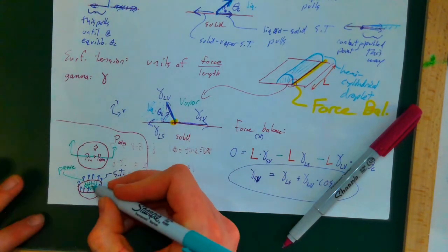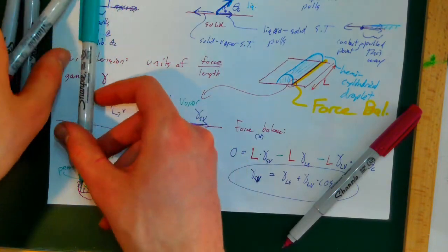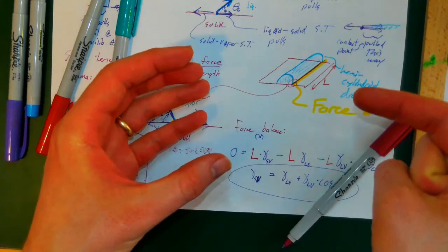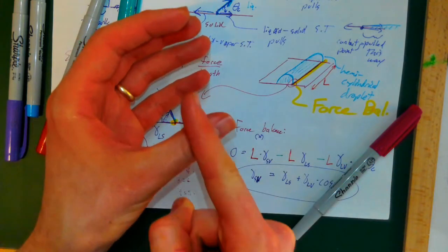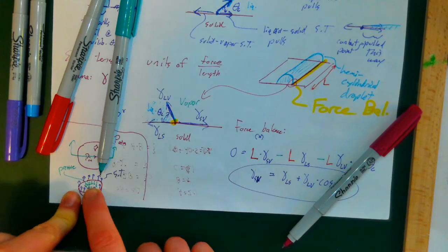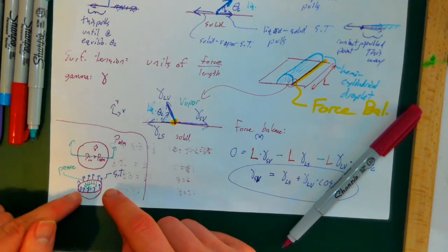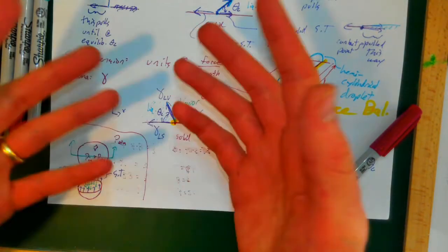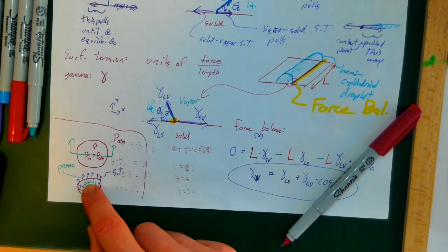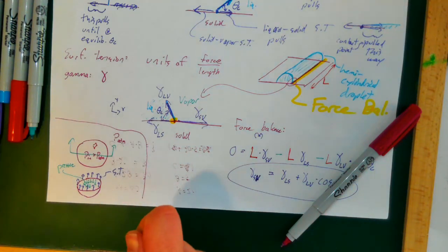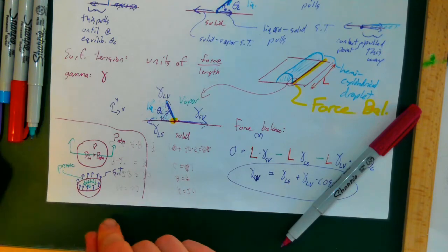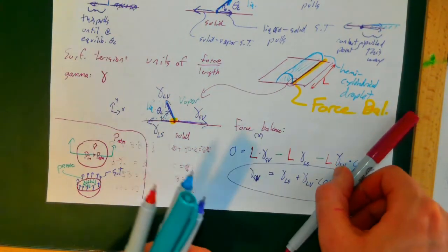So basically, pressure is pushing on the inside, and this happens both with bubbles, that's a thin liquid film with gas inside and gas on the outside. This is why when you pop a bubble, the bubble actually pops outwards. It's because it's pressurized inside. And this also happens with liquid droplets too. So if you're trying to create emulsions or things like that, it's actually higher pressure inside of a droplet compared to outside. If you were able to stick a little magic pressure probe in there, you would actually measure a higher pressure inside.